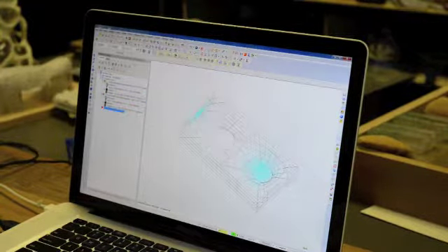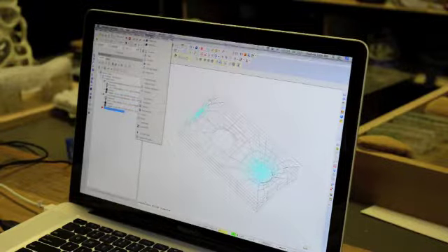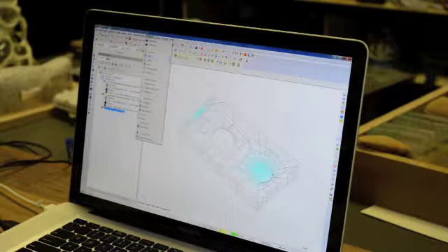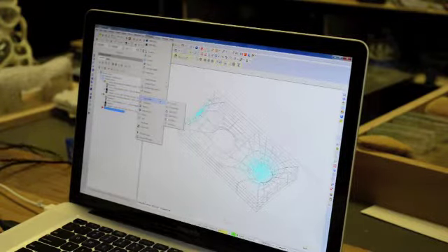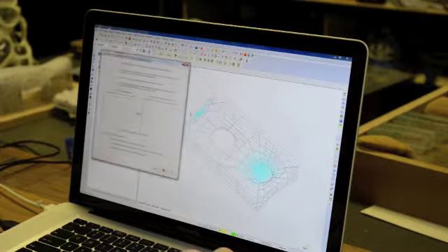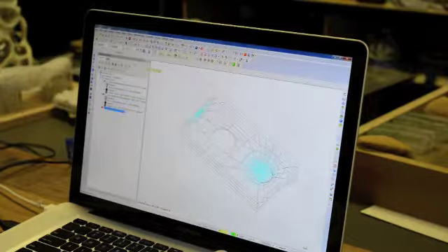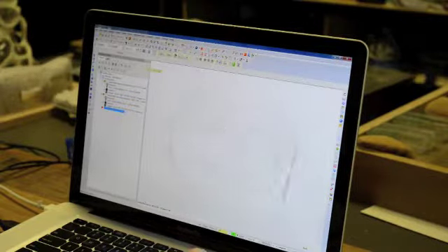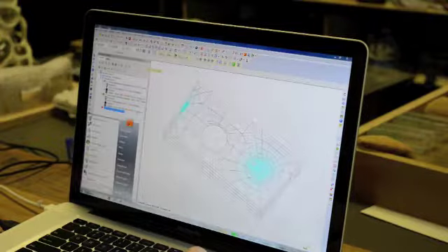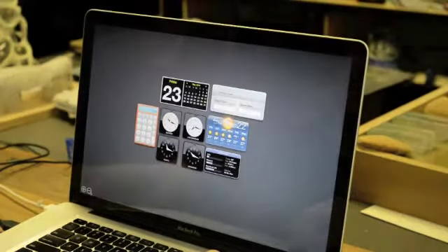So the next step is to do our finish toolpaths. So again, from the drop-down menu, toolpaths, we'll do another surface high speed. So this is going to pop up just telling you about some feature. Click OK, and then it's the same deal where we're selecting drive surfaces.